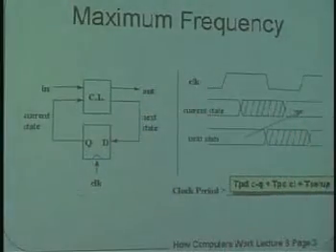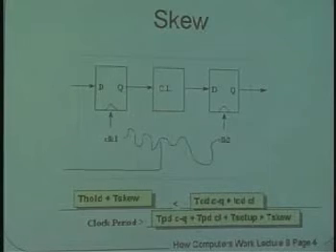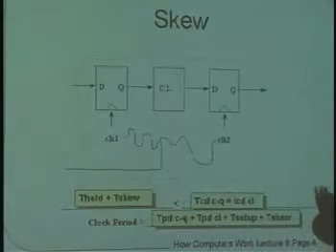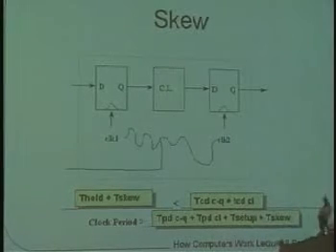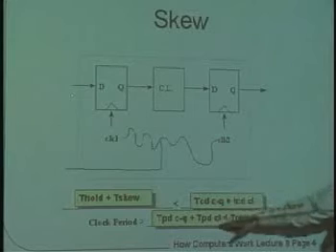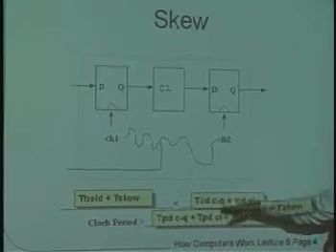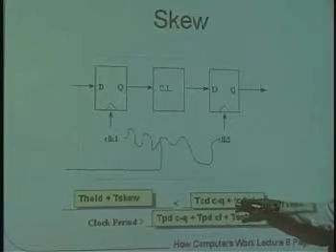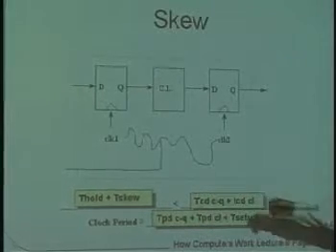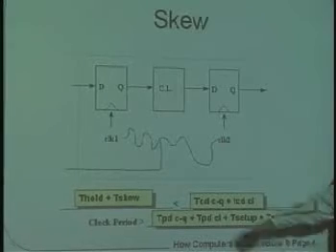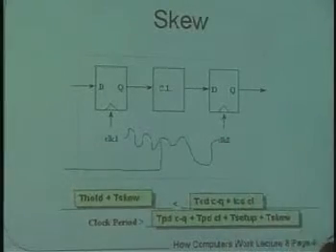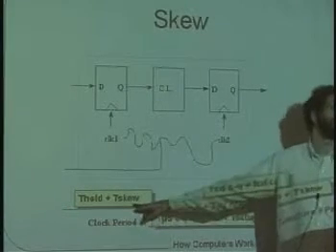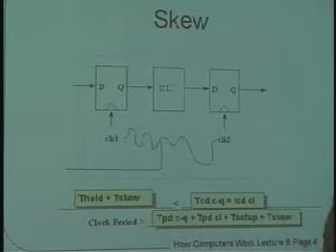And then finally, we talked a little bit about clock skew, and clock skew just kind of makes everything worse. If it's possible that this clock and this clock are not going to be hit at exactly the same time, we have to add a little bit of extra margin for the clock skew. And so these two relationships which we had before, all you need to do to understand how the clock skew makes them harder to meet is to put them up there and say, which side of the inequality should I put the clock skew on in order to make the inequality more difficult to meet? And the answer here is that you add the clock skew on the left-hand side, saying that we have to ensure that the contamination delays are greater than a number which is bigger than it used to be because of clock skew. Yeah? What does the squiggly line represent?